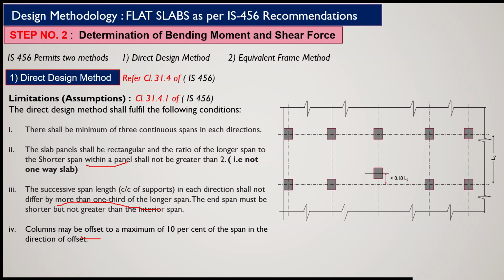Now offset is in this direction and the span length in this direction is L2. So this offset should not be more than 10% of L2.